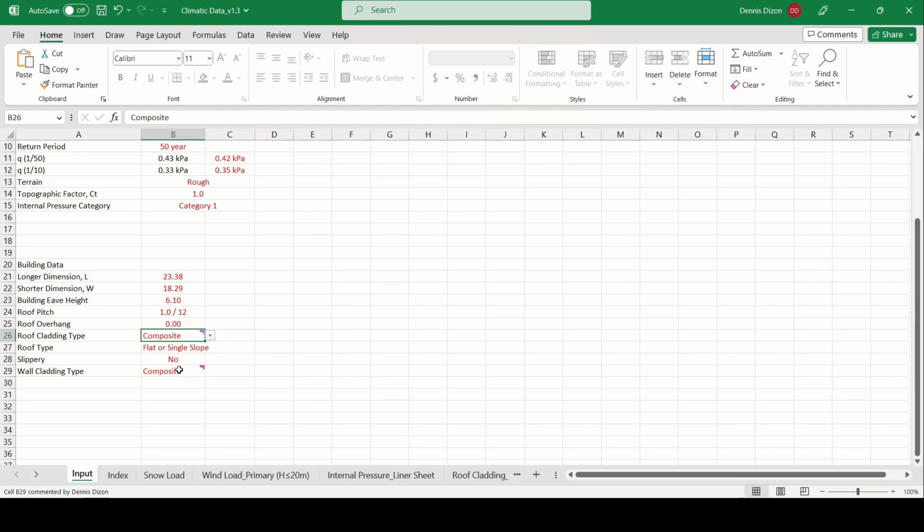if the architect would ask, like, what's the minimum purlin depth on this one, then I will use this calculation, like a preliminary calculation, to determine the possible depth, because I don't know what would be the final output from the pre-engineered supplier. At least we have an idea, and then we can say, okay, at this particular loading at this span, you have to use minimum 12 inches of purlins. I can also calculate the weight of the entire building for the seismic load calculation.